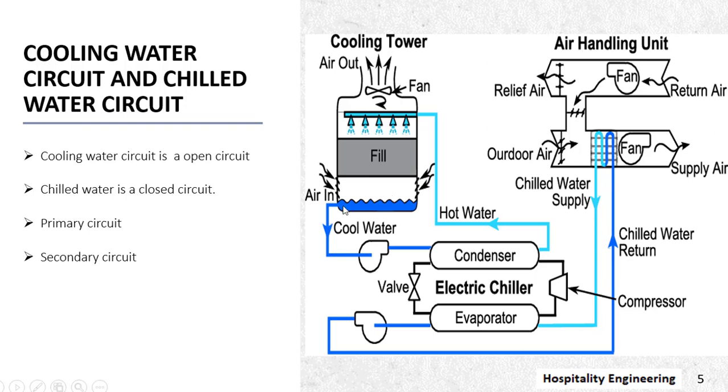Once this water is cooled, by gravity it comes back to the condenser water pump. Thus, the cycle is continuous. However, this is an open circuit. Chilled water is a closed circuit.